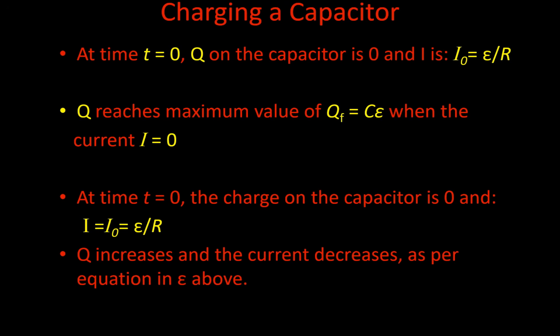Remember, your capacitor always adopts the voltage that the battery is giving to it. A 9-volt battery gives you 9 volts across your capacitor plates. So when the current, which is the charge flowing on the capacitor, becomes saturated, the current will gradually slow down. The charge per unit time deposited onto the capacitor will slowly reduce. Well, I say slowly, it's on the order of milliseconds in this case. It will reduce and eventually stop because the supply has reduced as the charge builds up on the capacitor.